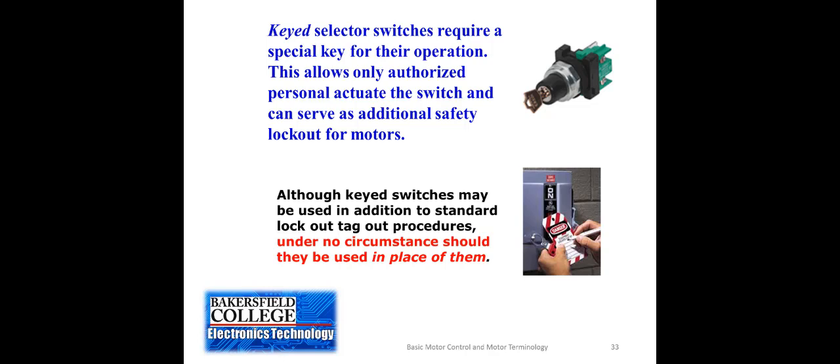There are versions of selector switches that are keyed so that only certain people can operate them, and that is those with the keys. You'll see that when you get into any elevator. There are selector switches that allow the fire department or public safety to move the key switch, the selector switch, into an operation of the elevator that either keeps the doors open, or prevents other people from getting on the elevator during a fire or emergency or some other purpose.